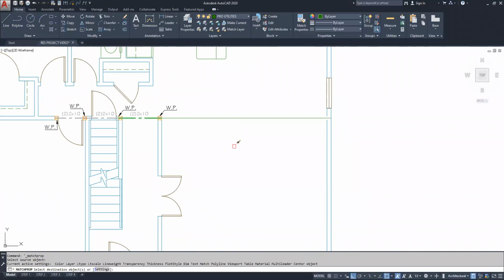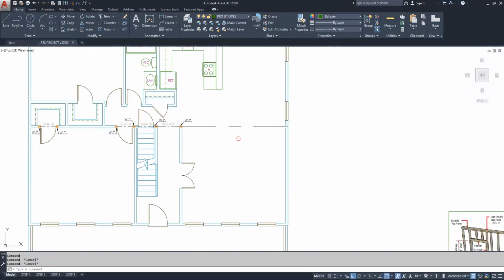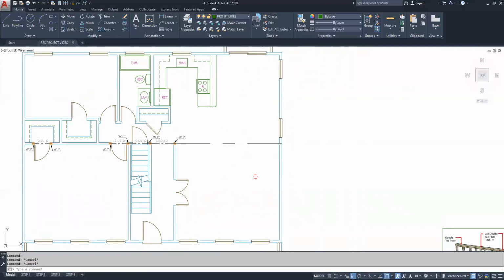It would be above our head so we can walk underneath it, but we'd have to put basically a bridge going from here to here. And the further the distance from here to here, the deeper this bridge is going to be. The further it's going to push down into the room. So you might not have a flat ceiling. It might be a drop right here, but you would still have a flat floor. So you might prefer to have this so the room feels a lot bigger.